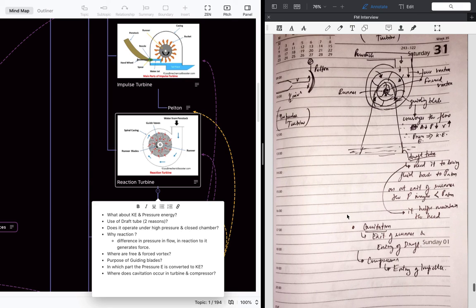As we know, there is a cavitation problem, as we've seen in the nozzle case, when there is a sudden increase in the area, the pressure increases from low pressure to high pressure. What happens is that when the fluid pressure is less than the vapor pressure, the water starts boiling.